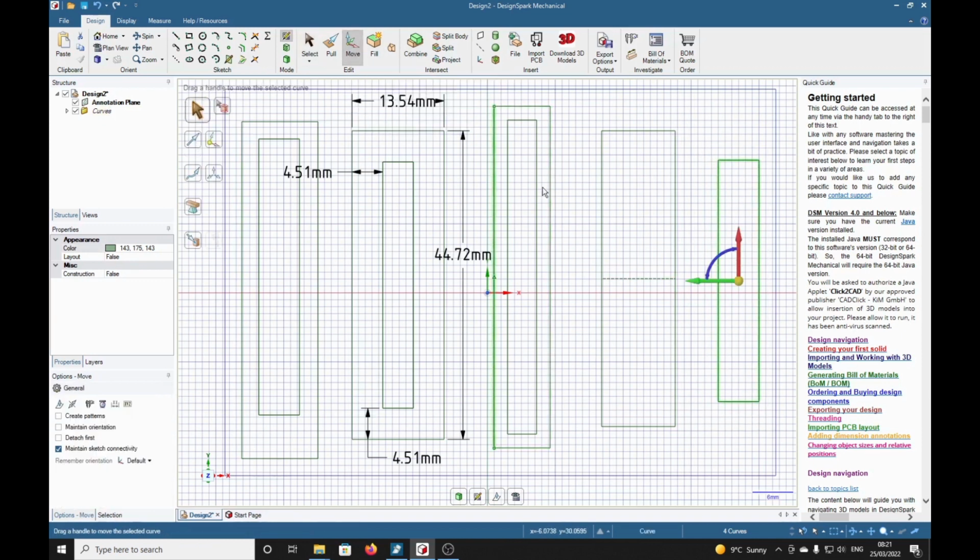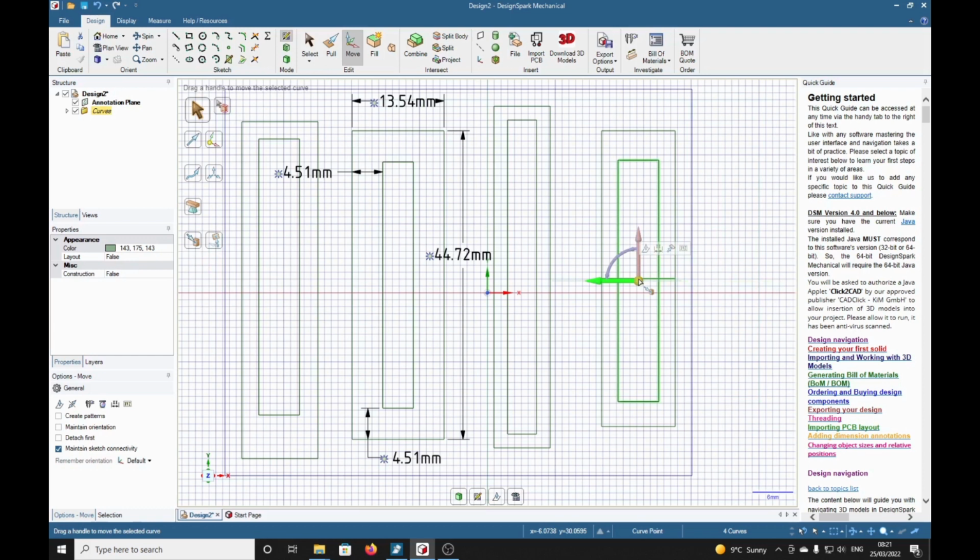and the move tool, we get our anchor point here. Select the green arrow pointing to the left, and the up to tool, up to there, and then touch on the triangle. That jumps into the center laterally, then go to the vertical one, select that, again up to and select the line, and it pops up the center vertically. And we can now just delete that.